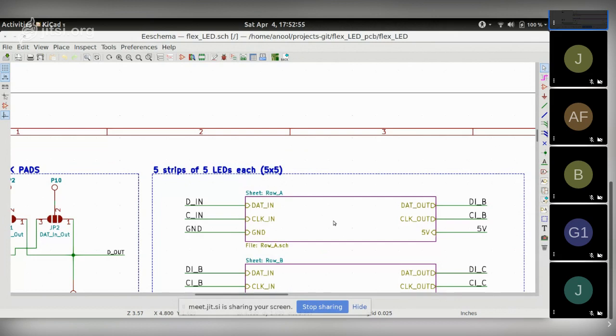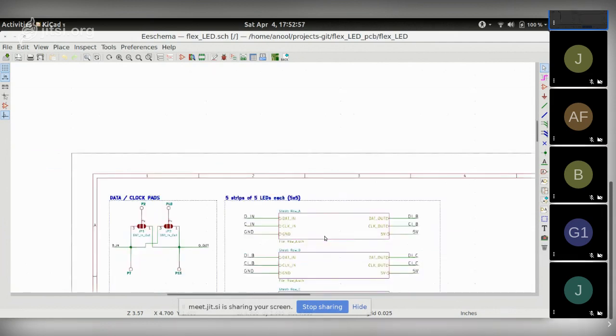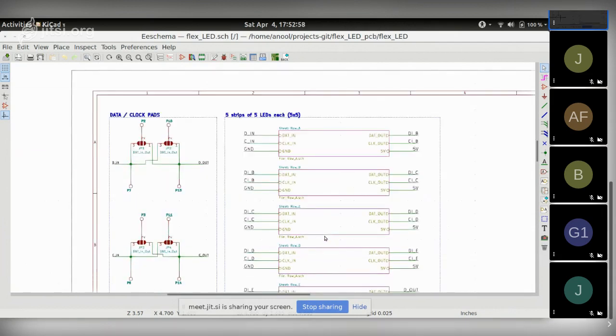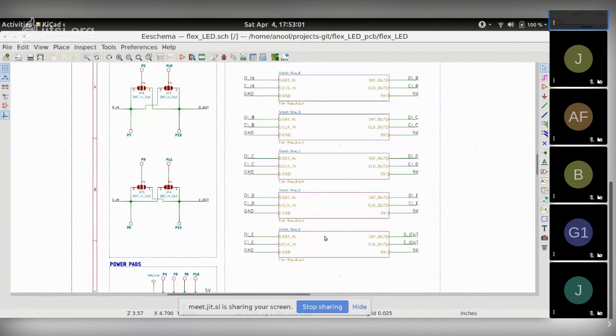It's a bit of a tricky thing if you end up with a complicated schematic. A global label is visible everywhere, so it doesn't necessarily appear in this kind of bring out over here, as you see. And that means you could either misconnect them or leave them unconnected. Obviously, when you run an error check, you might catch it, but not always.